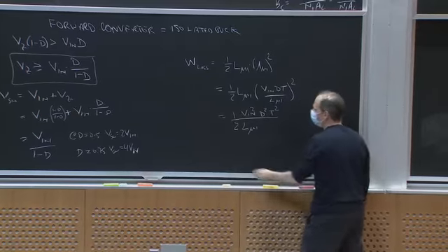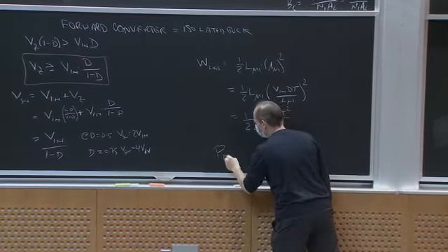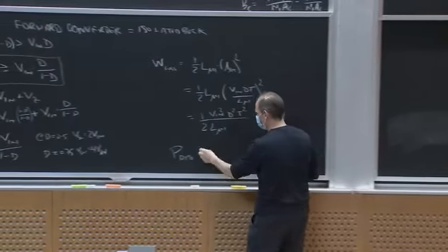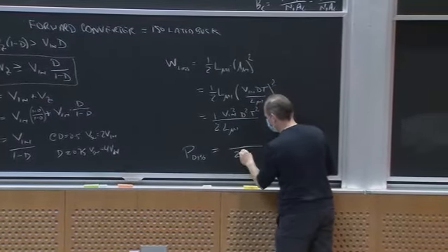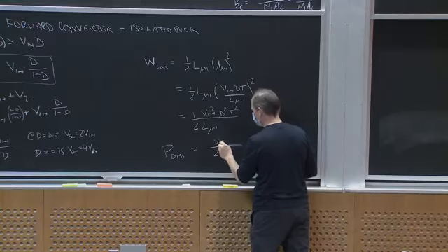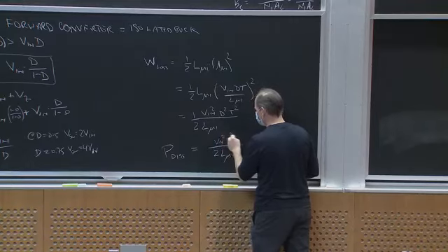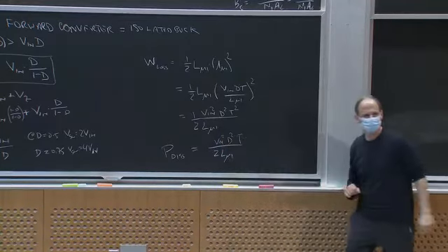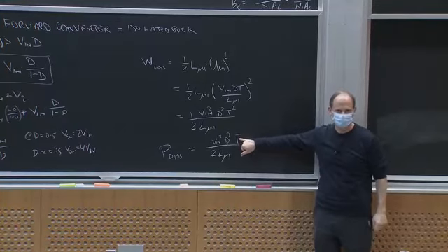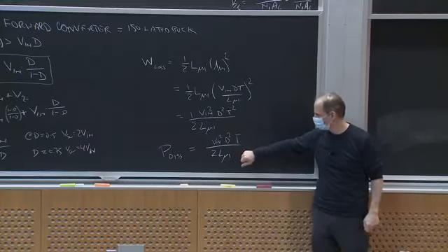And then if I wanted to say what's the power dissipation, I have to multiply that by the frequency of 1 over T, and what I get is V_in squared D squared T over 2 L_mu1. Okay? So if my T is really small or I have a high frequency, I dissipate very little energy in resetting the core for a given size.